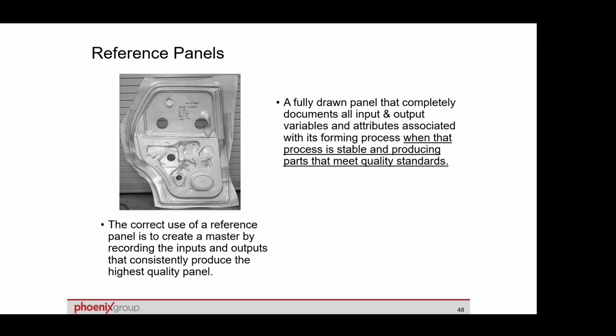It might be difficult for you at your customer plant, if they're not using reference panels, to do this, but you could ask a lab to hold those for you, or you could cut templates out of critical areas and make sure that you document on those templates the high strain conditions, the recipe at the time those were formed, etc. You can do that to help your problem solving efforts in the future.